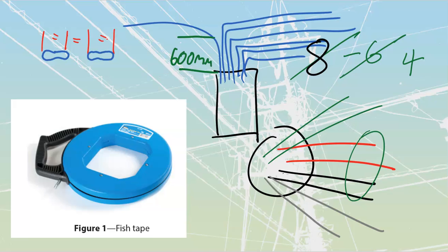Go through those examples. It's the same things that we're doing inside the video, but it's a layout where they're showing you what each of these is doing, and they're giving us different values that we're going to pull out. They're showing that if we have derating, we are going to need to increase the size of our cable to make up for the capacity that we have lost inside of them.